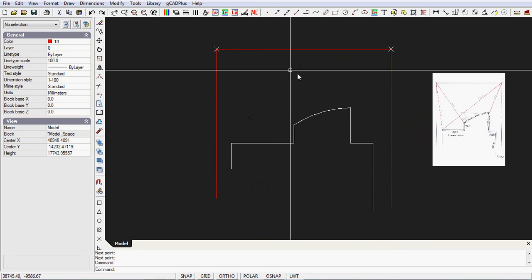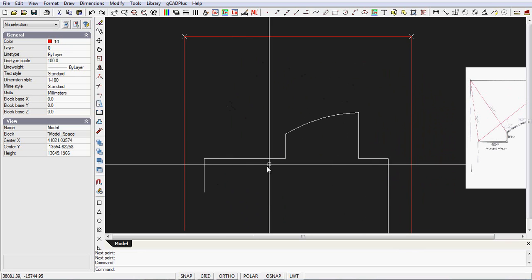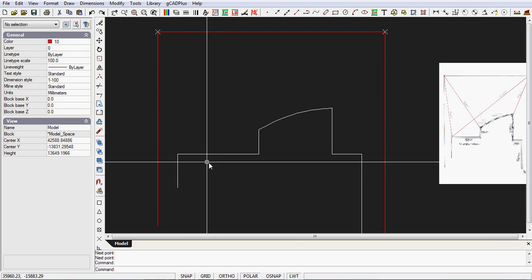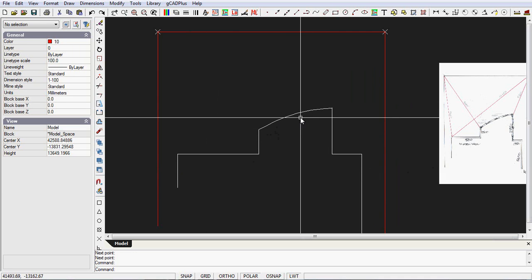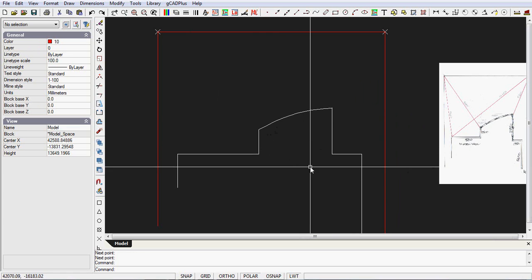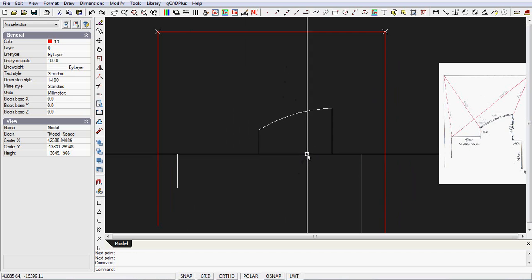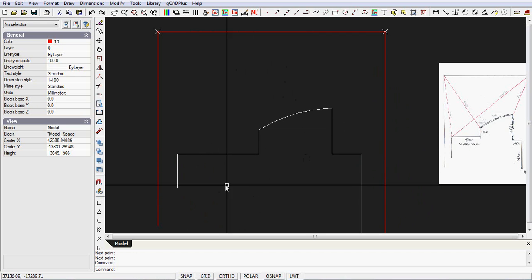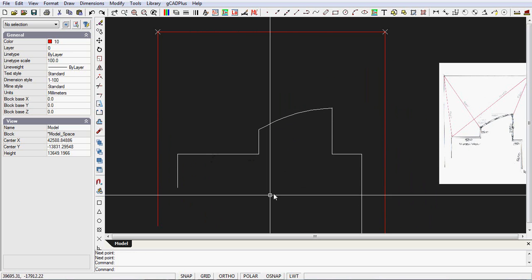We can do our landscape design in this quite small courtyard area. We have the footprint of the house in on our mud map. We know there's a window wall through here and a series of windows around through there, so we're going to be concerned with giving good views into the garden from that room there, which I think is a dining room, and a room here which I think is a sort of lounge family area. So you want very good views of the garden from this zone.